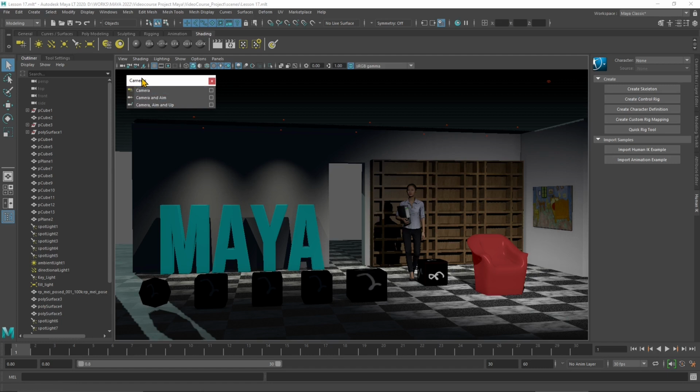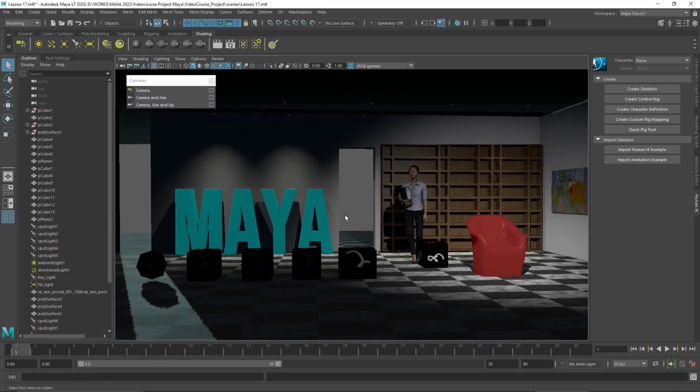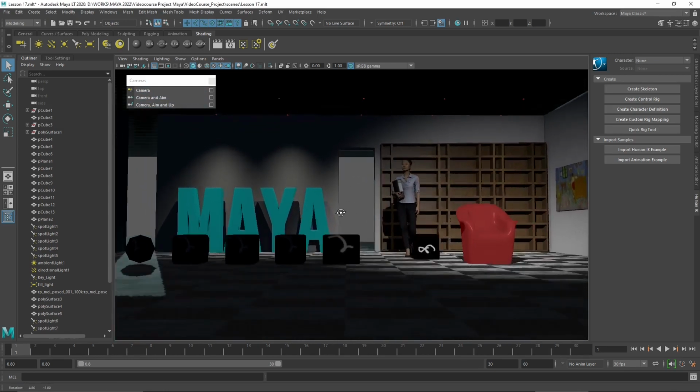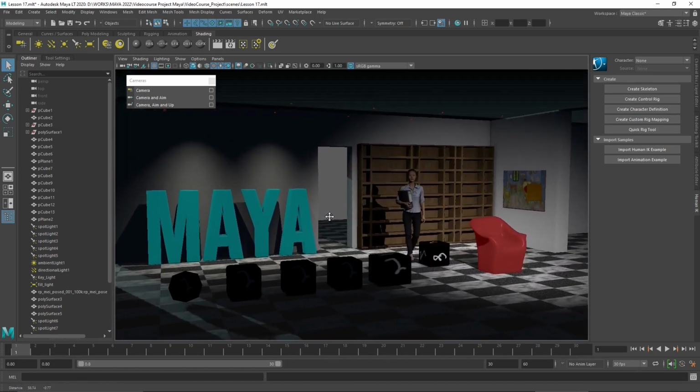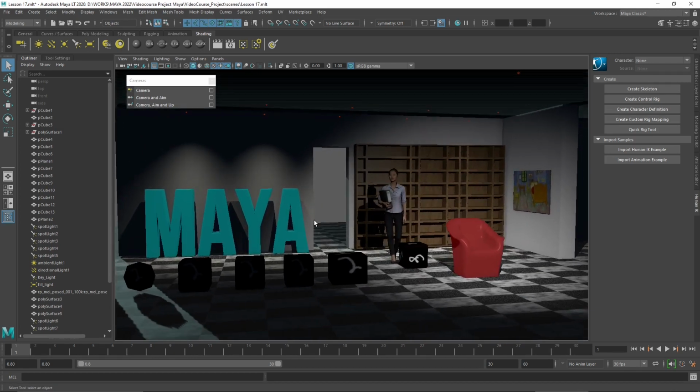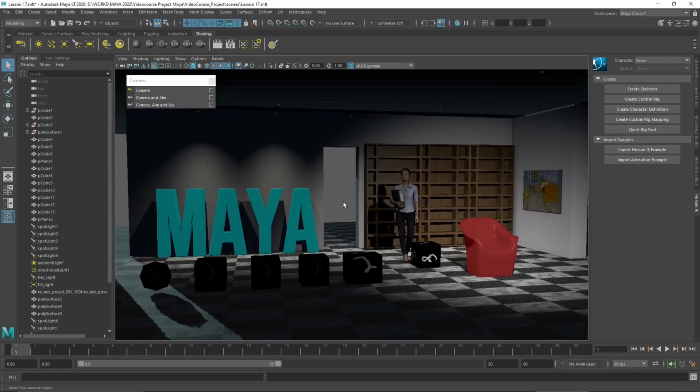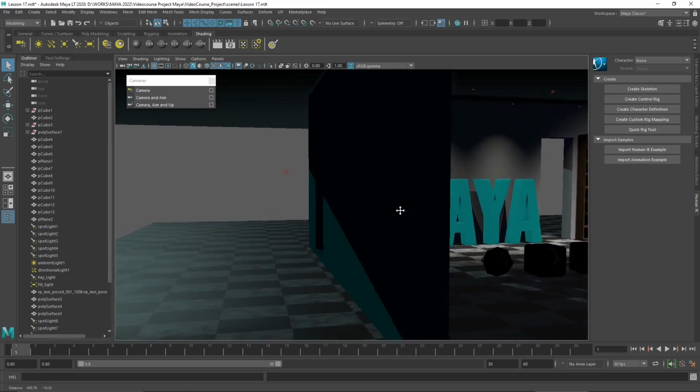So cameras are just like any other object that we can create in Maya, except that they are just used for creating views, basically, or points of view, and then we can adjust them a little bit, and we can set them up to use special effects that simulate reality, like depth of field and motion blur and things like that. Depending on how we set up the parameters, we can get different effects and different looks to our scene. We can also customize a little bit more what our output will be, which is usually a single static